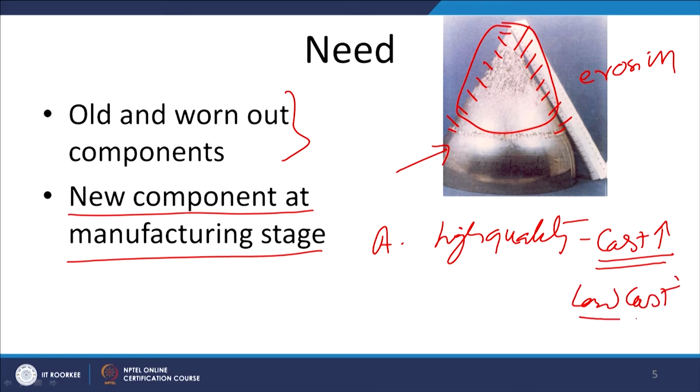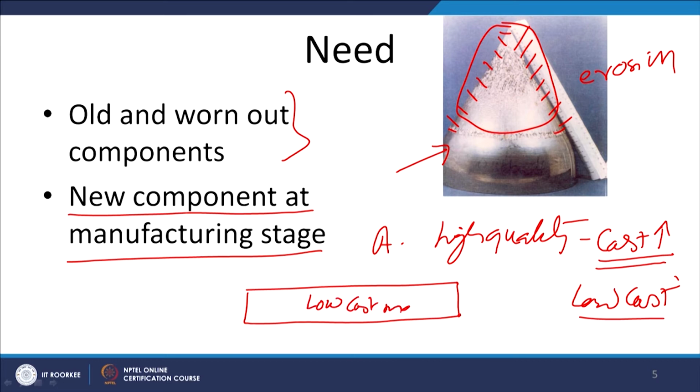So, for making the low cost, basically we choose a low quality material like simple mild steel, which comes out at like 40-50 rupees per kg, and with this low cost material, once the desired size and shape is given, its surfaces are modified or engineered so that it has the properties of those good quality materials that will be able to perform the required function for longer life.